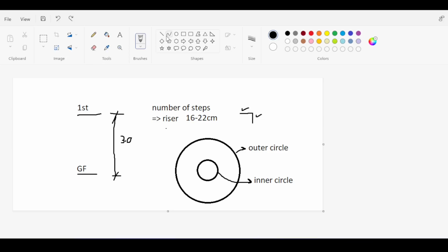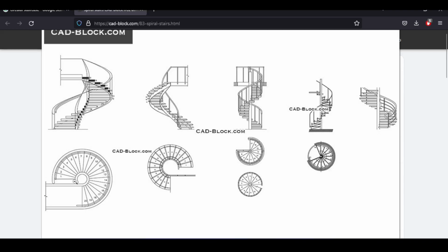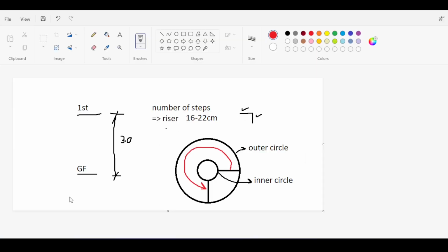Usually, our staircases have 270 degrees rotation. Of course, I'm saying usually, but it changes from one part of the world to the other. But I'm assuming now that my staircase is 270 degrees in rotation, meaning if it starts in this position, it will rotate 270 degrees and end in this position, perpendicular to your starting position. It looks something like the lower left one. You start going up, you end going to the left. This is a 270 degree rotation.